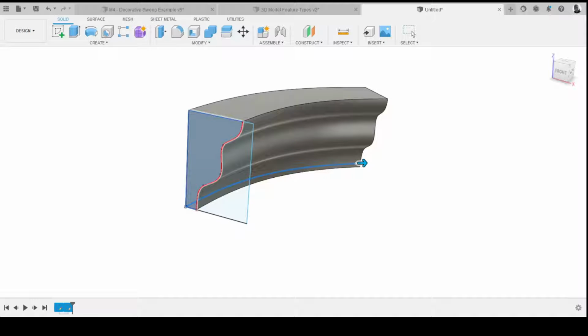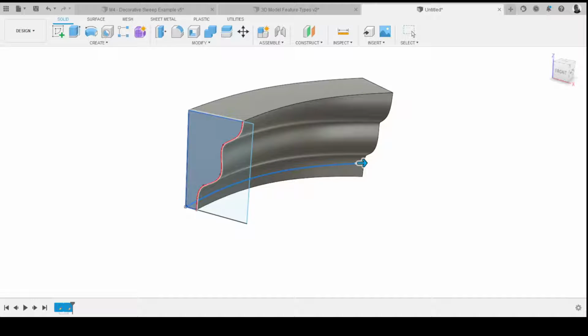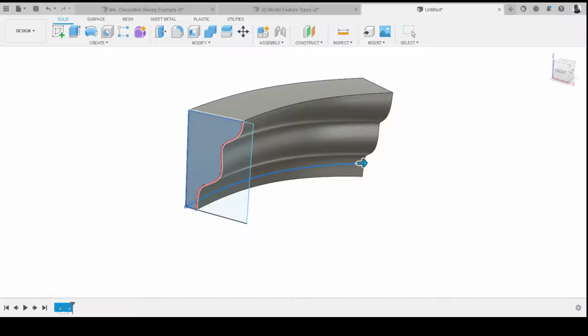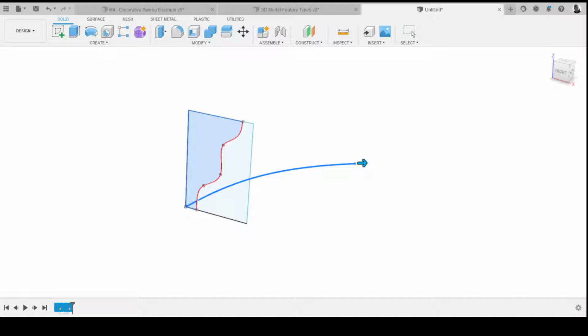You can also, just like extruding, taper things. So you can make things flare out and taper in, should you wish. Only occasionally useful, but occasionally very useful. So you can do a minus or a plus to make it taper in or taper out. And again, it will tell you if it can't compute something. If you try and taper something in particular, and it can't sort of compute that, those paths would start intersecting again.